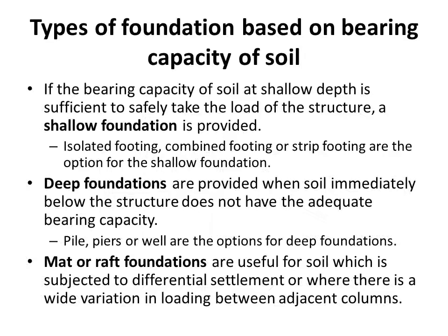Deep foundations are provided when soil immediately below the structure does not have adequate bearing capacity. Pile, piers, or well are the options for deep foundation. For example, deep foundations are provided for bridges, dams, etc. Mat or raft foundations are useful for soil which is subjected to differential settlement or where there is wide variation in loading between adjacent columns.